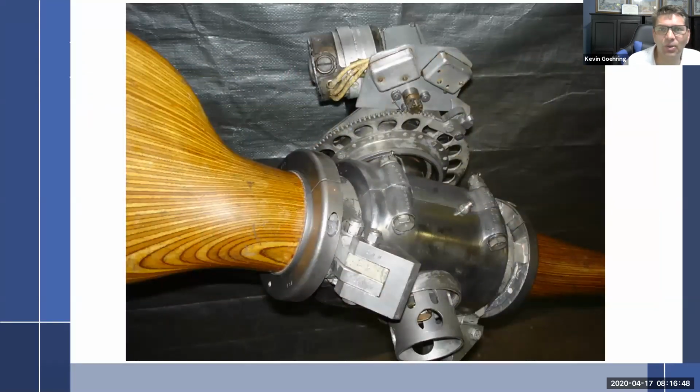adjustable. And this particular one has a little electric motor up here, and we'll talk about that later. It turns this little pinion, which would turn this gear, which would rotate the blades. And so the pilot could select a higher pitch or a lower pitch out of the blade, which is, again, actually a blade angle, but higher and lower blade angles as the pilot suited, but it was not constant speed.